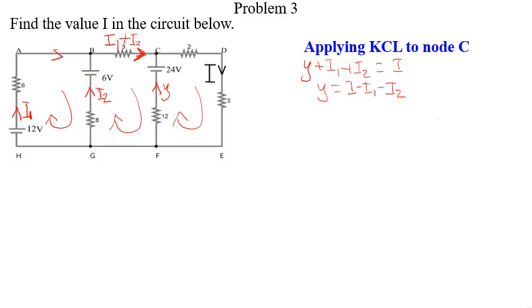So we have our 12 here minus 6. Then let us look at the voltage drop. Voltage drops are 6I1 because wherever there is a resistor, that is where we consider it to be a voltage drop, because voltage is equal to IR, current times the resistance. So voltage drop will occur here and another voltage drop will occur here. But let us look at the direction.